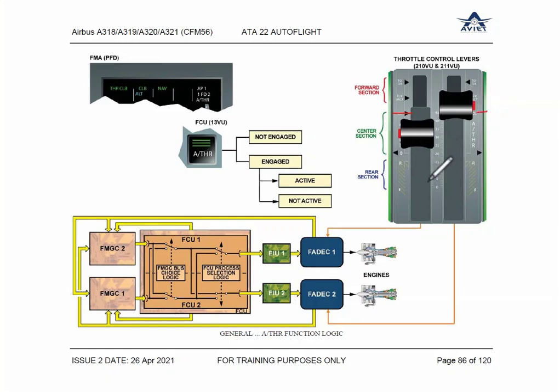Now, the FMGC is calculating the auto thrust because it is in engage and active mode, so it is applying the thrust based on calculation.